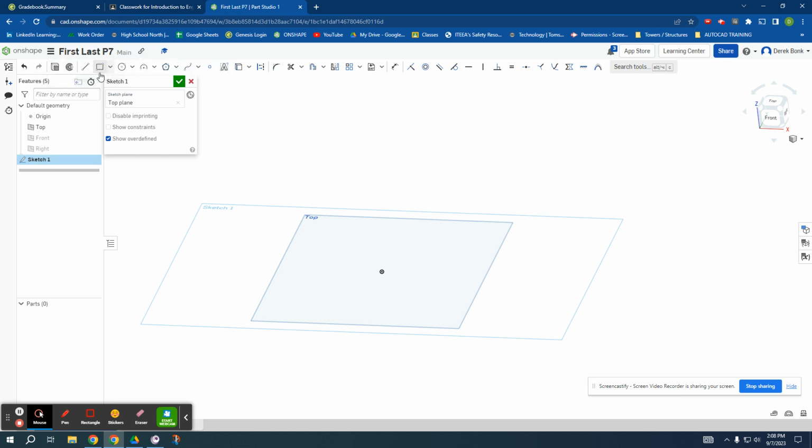Before there was feature tools, or ways that you can model and sculpt solid objects, this menu has a whole bunch of different tools, and some of them, in this case especially, you need to use a drop down option. There's two kinds of rectangles. There's an aligned rectangle also, but two standard rectangle styles, just dragging from the corner and going point to point, or clicking in the middle and then dragging outwards and then clicking again to do that. So this is one we want.